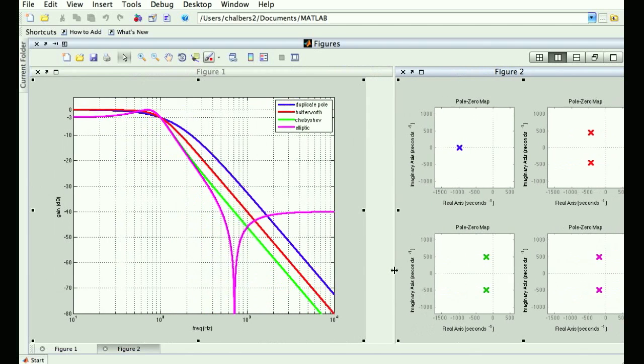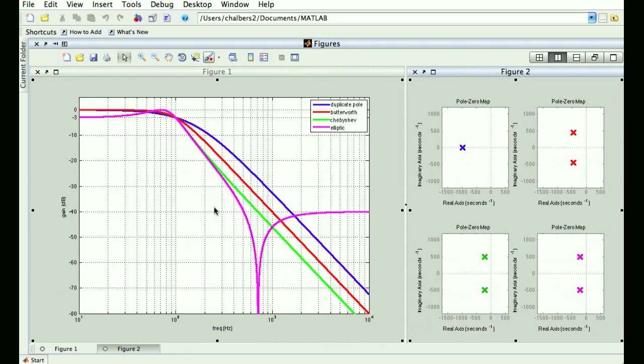So the elliptic filter, the way it works is you say, for the pass band I need at least 3 decibels. For the stop band, you only need to reject up to 40 dB. Okay, so it's not that great in the stop band. But the advantage is it's great in the transition band, right? It's outperforming everything in the transition band in exchange for not really caring what happens deep into the stop band. But again, that may be a deal you're willing to live with.